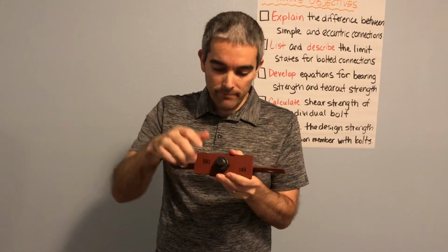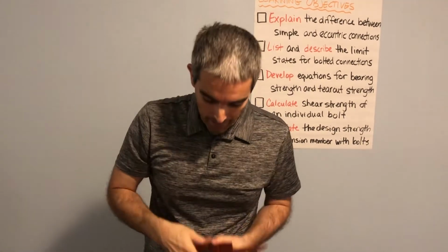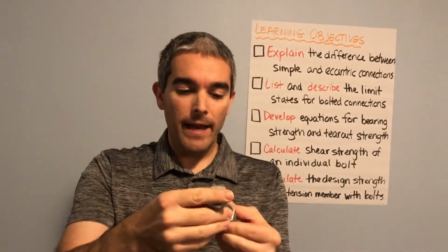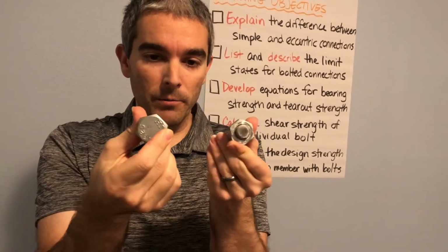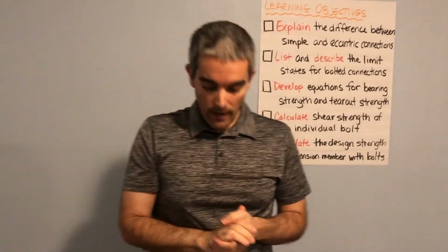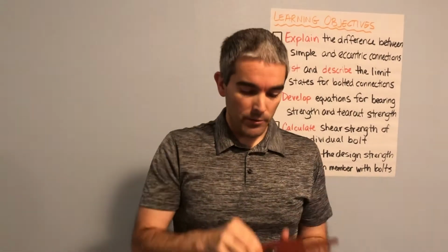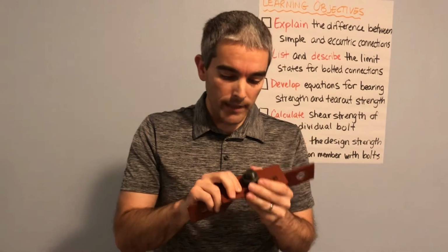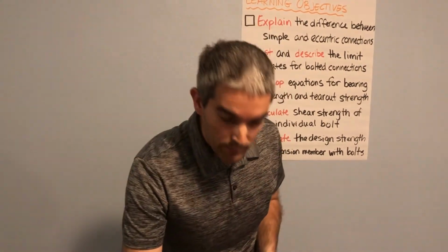One is that the bolt will simply shear apart, right? So that's what we consider bolt shear. As we pull on that, the bolt would physically separate across itself, and that's going to be in shear. So we're going to definitely have to check bolt shear. But what are some of the other things we can do? What if the bolt is super strong relative to the plates? To help us with that, I want to visualize what that would look like.